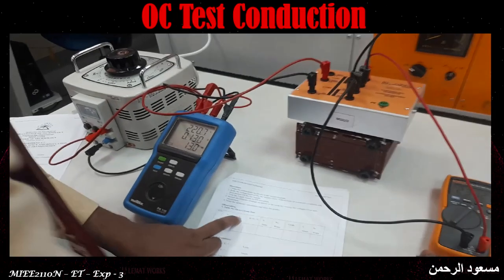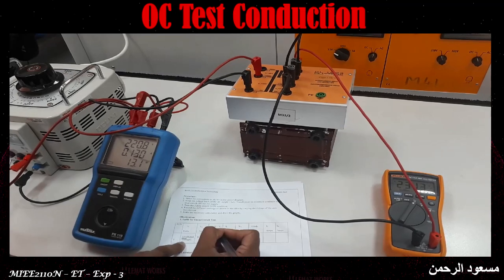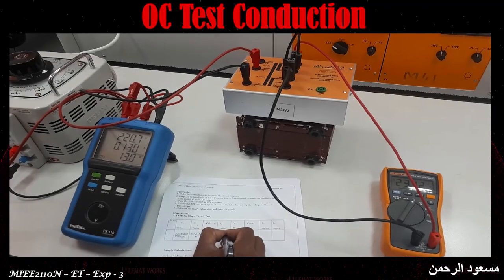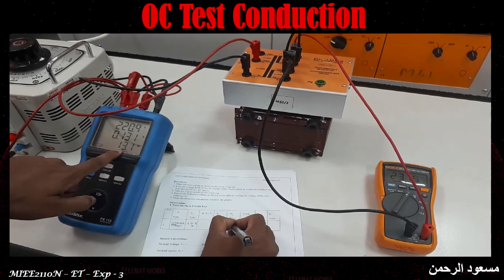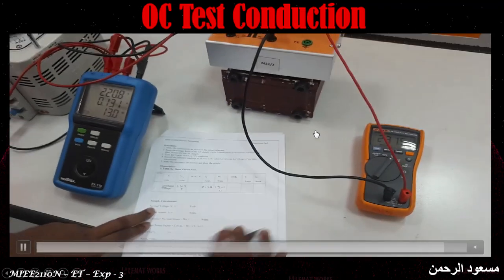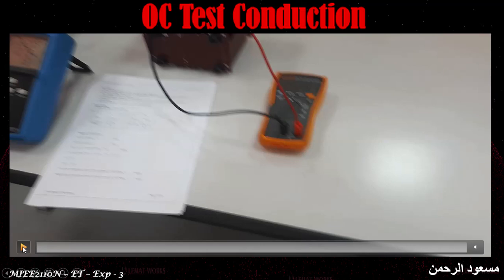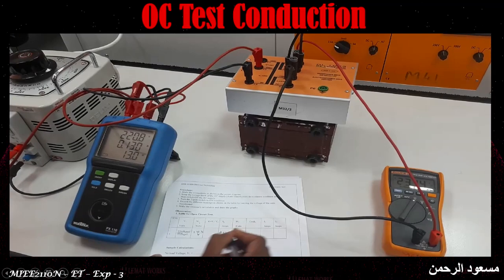So V1 is noted in the given table. V1 is 220.8, V2 is 231.2, and I0. This is called I0 because it is no load test. Already we have seen this. And the wattmeter reading is taken. You can see it to be 13.1 watts.